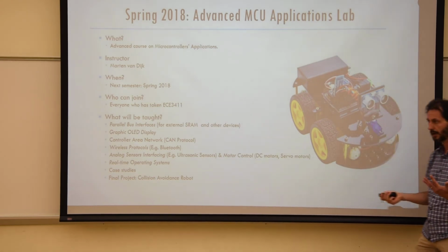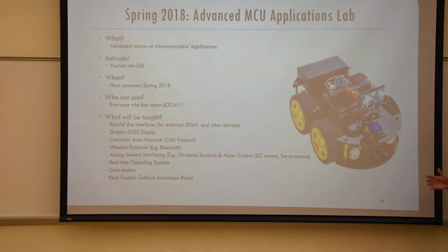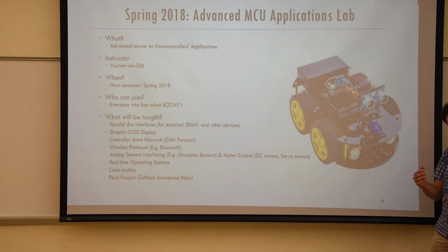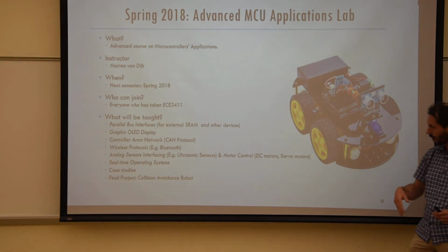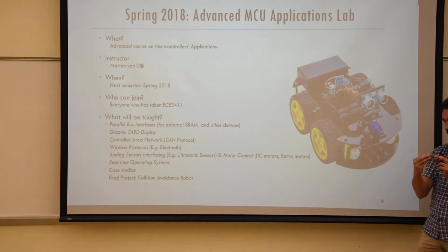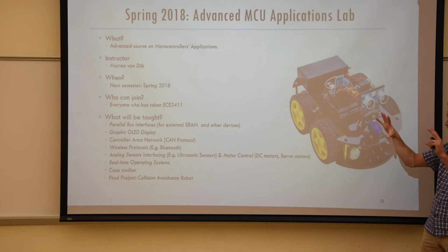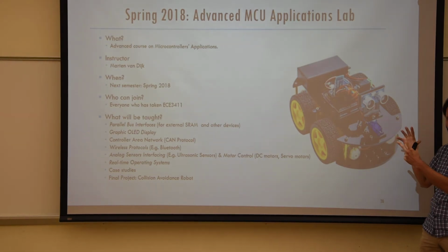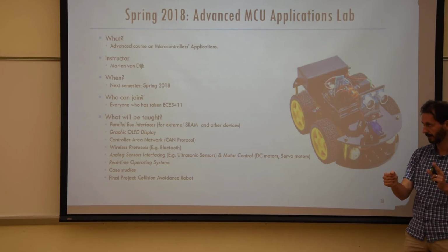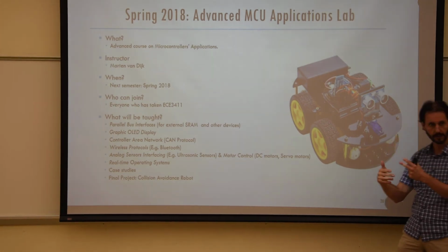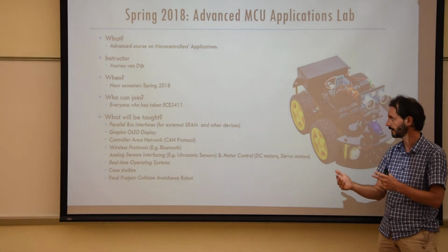Yeah, you just need to first of all put the hardware in the right way with the proper decoder logic, but then you also know that in order to talk to your external SRAM, I need to follow a certain sequence according to that timing diagram in the data sheet that we just saw. So you will be waiting for a little bit, and then you will be setting a certain pin to high and then low, and then you can do your writing or your reading and so forth.